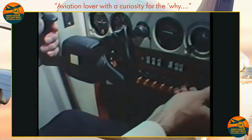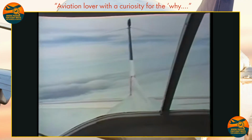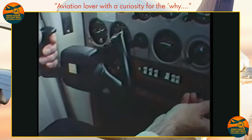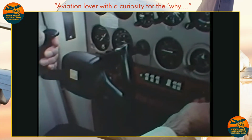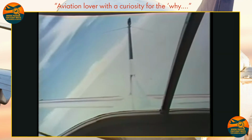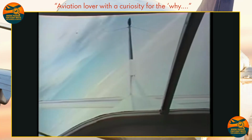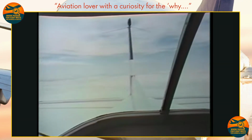Lift and weight are now in balance. And so to control the aeroplane in the turn, the pilot first applies aileron and a little rudder. In a steep turn, the pilot increases the angle of attack by gradually pulling back on the control column and opening the throttle to increase thrust, so that the vertical component of lift still equals weight. Then when we come out of the turn, we reduce both angle of attack and thrust to their normal values in straight and level flight.